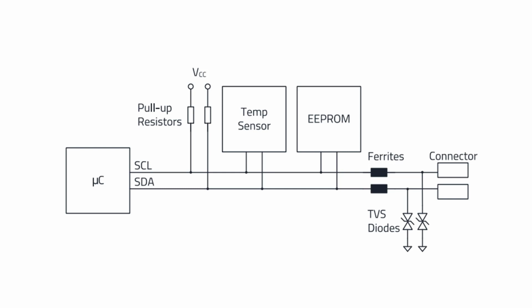Since the values of the pull-up resistors are often in the kiloohm range, the RDC, as well as the impedance of the surface mount ferrites below 10 MHz, only play a minor role here. This means that in a first consideration, it can be assumed that the edge rise time of the useful signal is hardly influenced in practice. But if you select suitable TVS diodes with low capacitance, their component capacitance also has no relative influence on the signal quality. During an ESD test, for example, a current of more than 10 amps can flow briefly, which then leaves a voltage of about 10 volts at this diode.